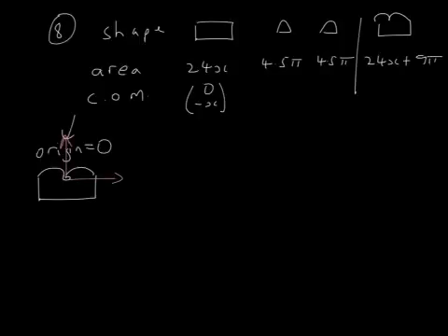Centre of mass of the semicircle, well, they tell you that the centre of mass is at 4r over 3 pi, and seeing as r is 3, that's 12 over 3 pi, or 4 over pi. So it's minus some number, which I'm just going to call p, not really bothered about that. And then the y coordinate is 4 over pi. And the centre of mass here we're going to call x bar, y bar. Now clearly the x coordinate of the centre of mass is going to be 0. It's going to be slap bang in the middle. It's going to be along this line here.